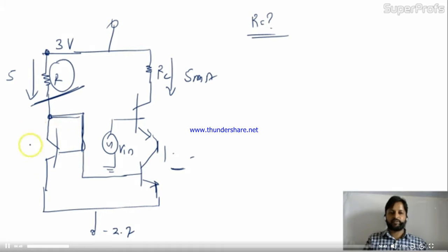Now, if you observe this circuit, this is the current mirror circuit, where it's Q1 and here it's Q2. Now the question is, to make it a constant current device, what should be the value of R? And the 5 milliampere is given over here in between. Okay, friends.